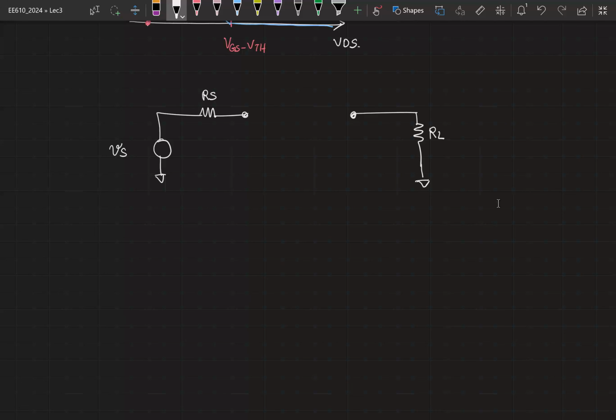Okay. And if the transistor is in saturation region, what all do I have to model? Y11 and Y12 are 0, right? I have Y21, which is some GM times VGS, where VGS is between these two terminals. Right? And do I have anything else?